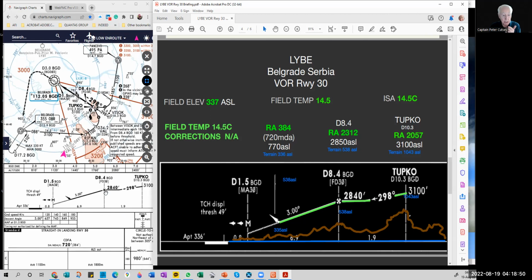Also, at this point, you've got a beautiful wind vector on your nav display. That's where you call by the final fix, and you make sure you get a wind from the tower. Well, in our example, we're going to fly today. The wind at the surface is 210 degrees at 30 knots. The runway is dry, so it's a 90-degree crosswind. If the wind at your altitude on your little wind vector on your nav display is considerably different, you can expect wind shear. So final fix means last chance. All right, so this is ideal.